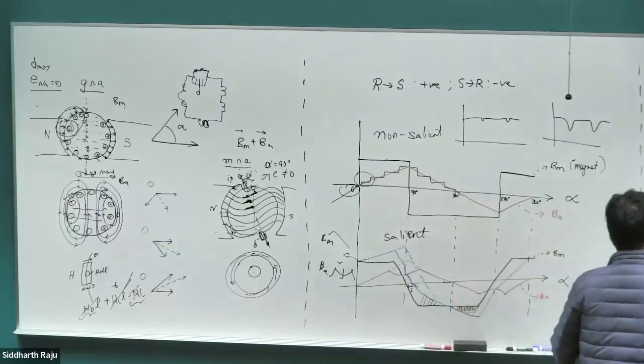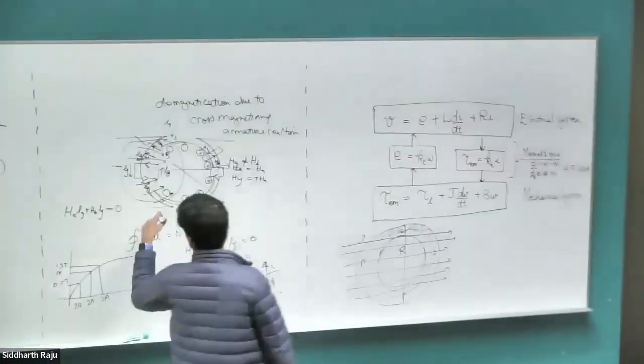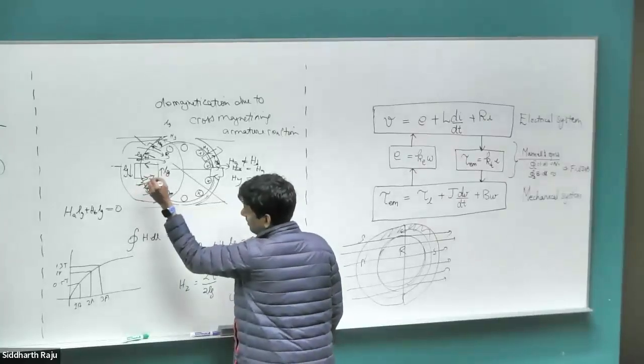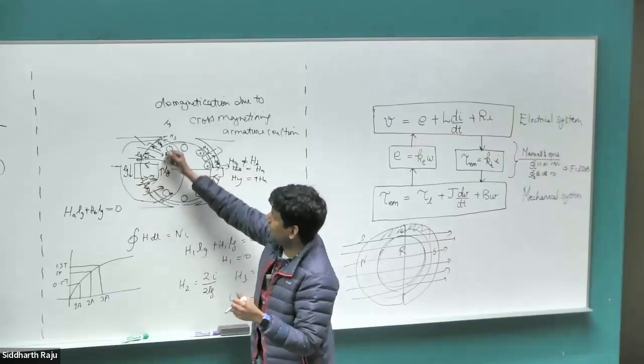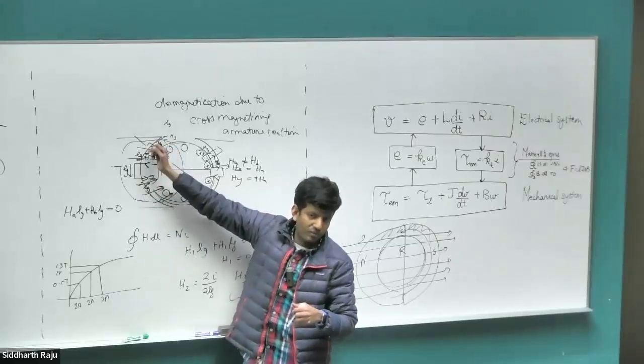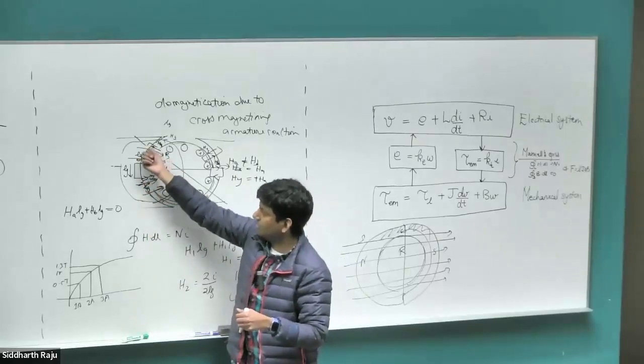In fact, when we have this phenomenon, the amount we gain due to the magnetization factor, right? So these field lines are increasing the magnetic field, but the amount increasing the magnetic field is not proportional to the amount they demagnetize the magnetic field because of the saturation. Because of saturation, this does not increase as much as this has fallen.